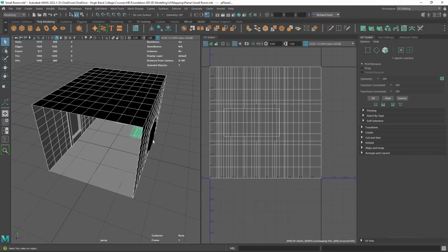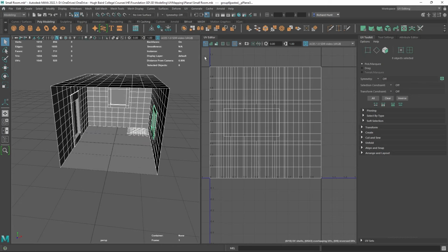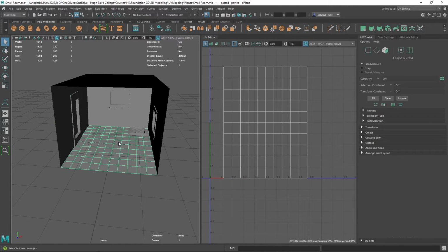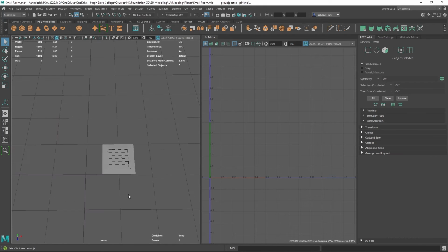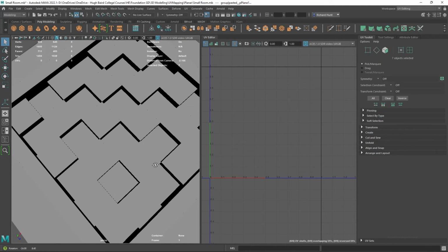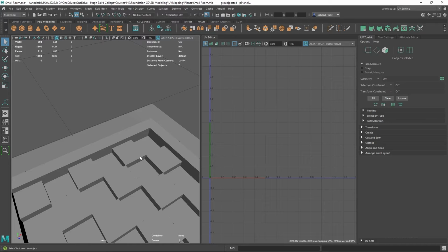Now the reason behind that is you will notice that all of the UVs for the other components are showing up on my floor one. I need to get them completely deleted off it. It's just so that each UV set only corresponds to the thing that it's named for. So this is now purely for the floor. Now that I've done that, I can hide everything I don't want to UV map next, just leaving myself with my little grid here. Now you'll notice that my grid is a bit more detailed in its modelling than the floor was. There's actually a bit of a drop in it, a bit of depth to it.